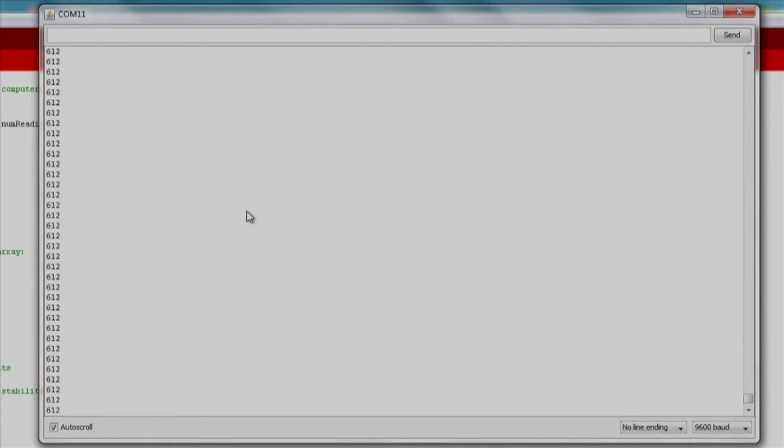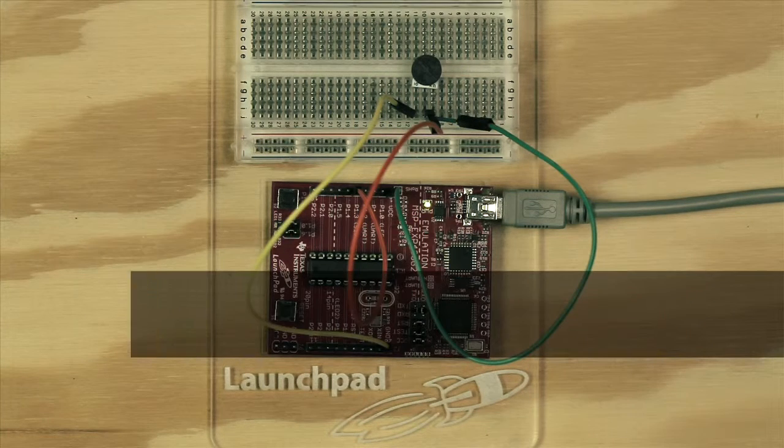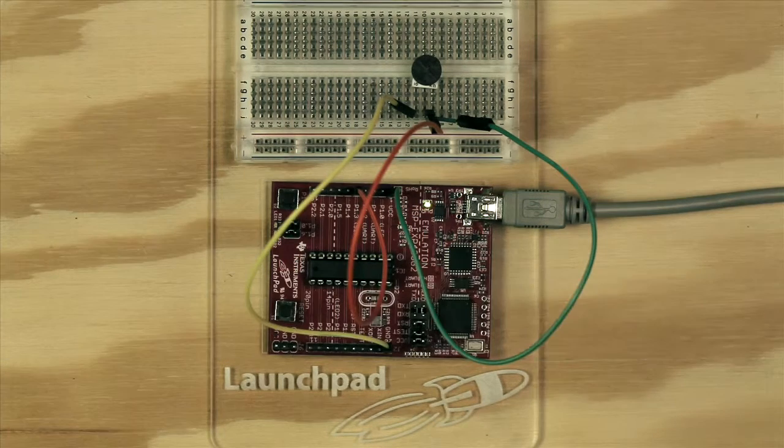To display the results of the LaunchPad on your PC, we can either use the serial monitor of Energia or use an IDE like Processing. Now let's get started to see how this works. In this tutorial, we use a potentiometer as analog input. In order to read this input voltage, which ranges between 0 volt and 3 volt, we can use the analogRead function. To send results of the LaunchPad to the PC, we must establish serial communication using the serial port. We will show you how this is implemented.